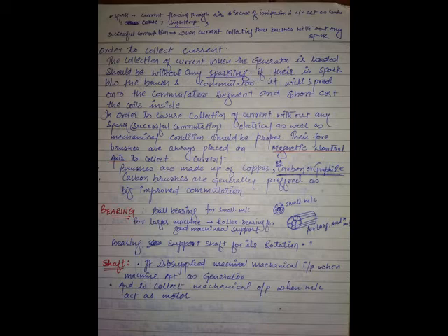You can't simply connect like this. It should have a diamond shape, a V shape coming like this. You can't simply cut like this, because mechanically it's not correct to bend like this. The coils are formed in a diamond shape like this. So some part is coming out, yes or no?